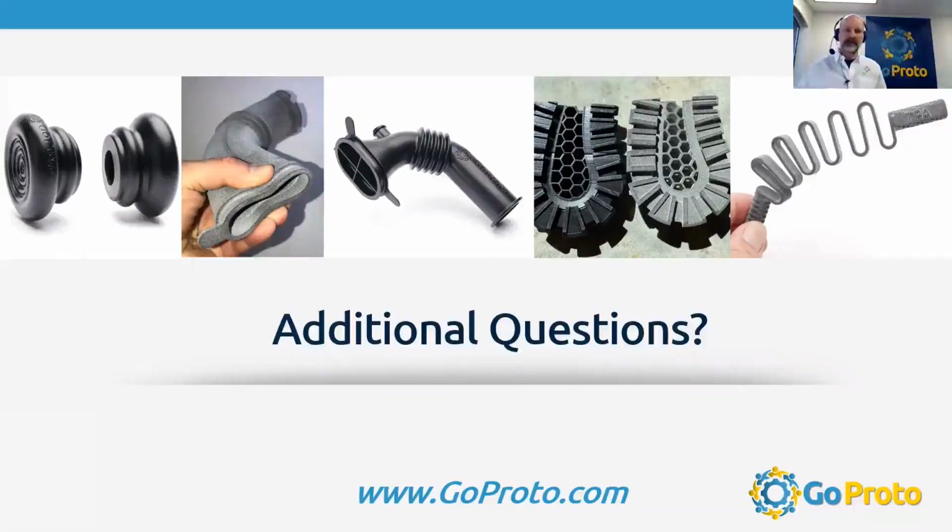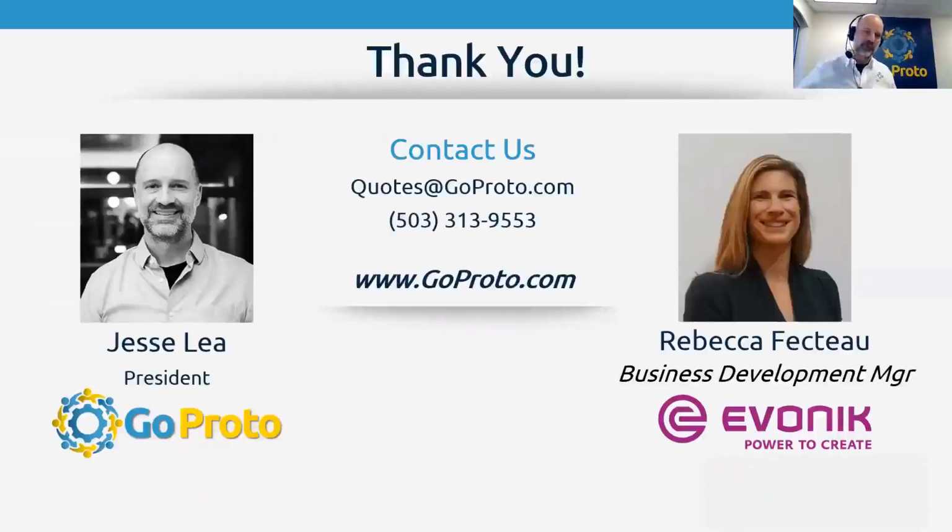That's in development because this is a new material, and that idea is newly being developed. It's going to be a let's-work-together-and-get-it-figured-out situation. But yes, we're working with nTopology, some of you may have heard, and General Lattice to do exactly that: material libraries to help with what is essentially FEA, to be able to take a design and apply some design constraints to use the computer and the programs to quickly make lattices that achieve the same durometer that you're looking for. So yes, we can try that. And also, as I mentioned earlier, finding the Goldilocks, printing several different versions in one print quickly and inexpensively, can allow you to test a bunch of different versions at once for low cost.